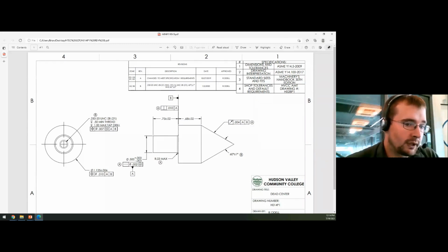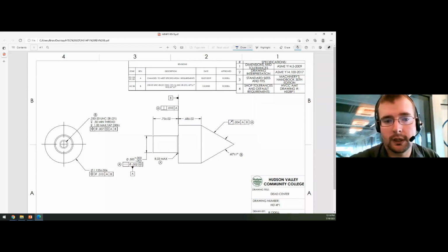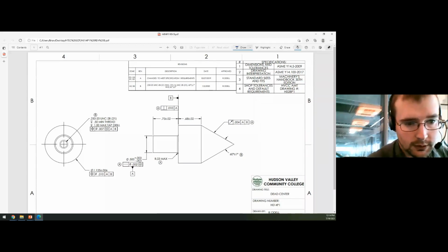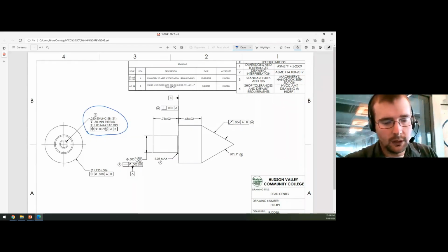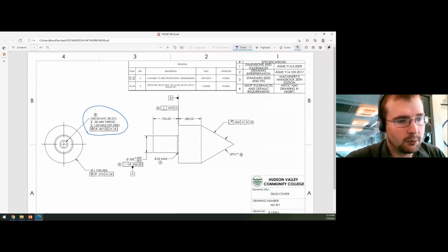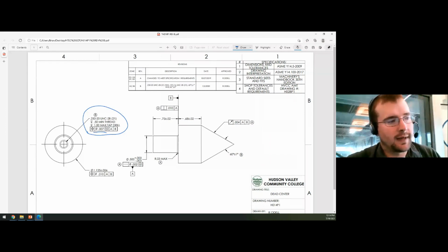We have all different ranges of tooling. This example is sort of interesting. One thing I always point out, and I am drawing on the screen here: when you've got a thread spec, technically that's the pitch diameter, and it would be nice if the engineer went to minor and they could put the note here. And that's a conversation that comes up in print reading, and why you can do that.